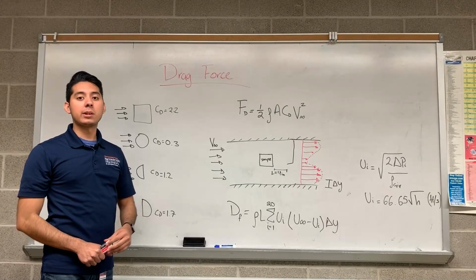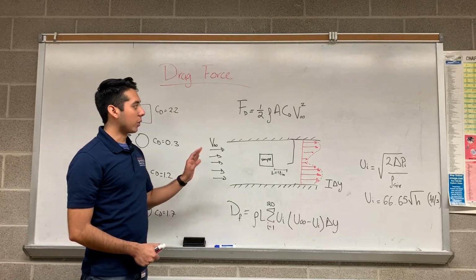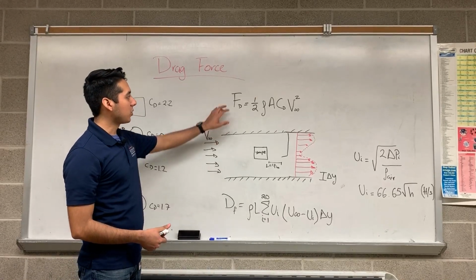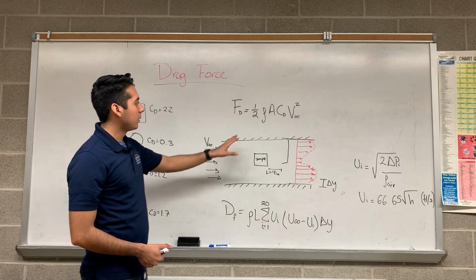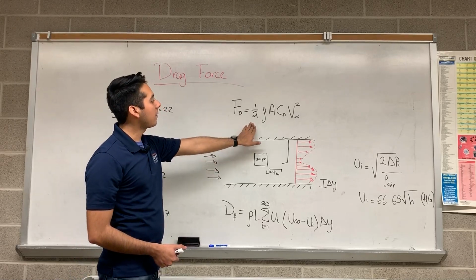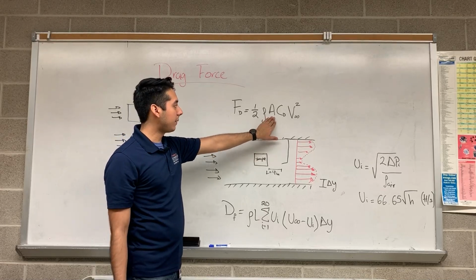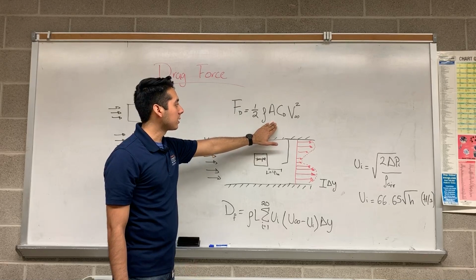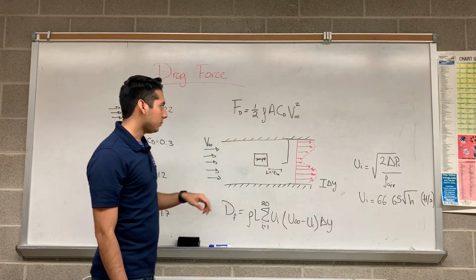So for the analysis part for your drag force lab, we're going to have our 2 equations. If you see them over there in the procedure manual, we have equation 1 and equation 2. Equation 1 is 1/2 times the density of the fluid, in this case air, times the frontal area of the shape that we're using, the different rods, times the drag coefficient times the velocity squared.